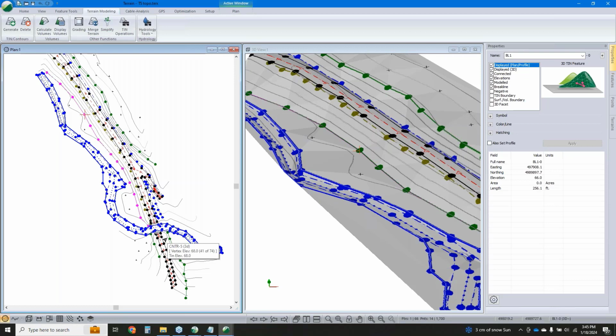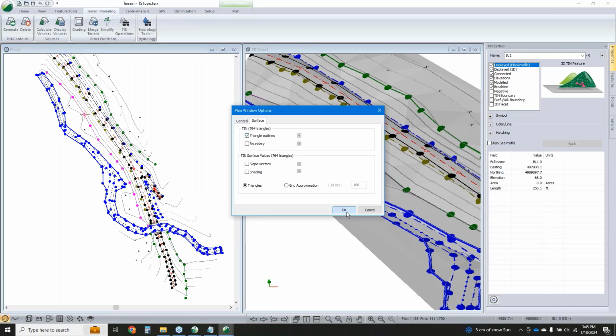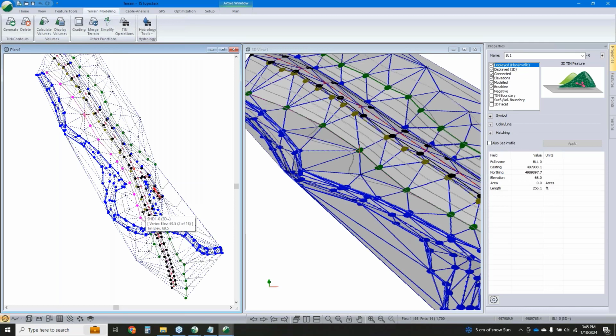Another option, if you don't like LandXML for whatever reason, you could turn on the wire mesh, and you could export that wire mesh to define the surface in another program as a DXF. And if you're working with something where you want more of the 3D solids type format, you can export it as an OBJ. So, yep, all sorts of compatibility. Yeah, and I think the same holds true for exporting from the location as well. You can save your alignments out as LandXML to preserve their geometry.